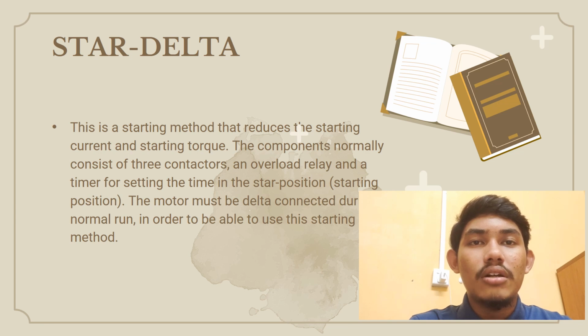Applications with a load torque higher than 50% of the motor rated torque will not be able to start using the star delta starter.